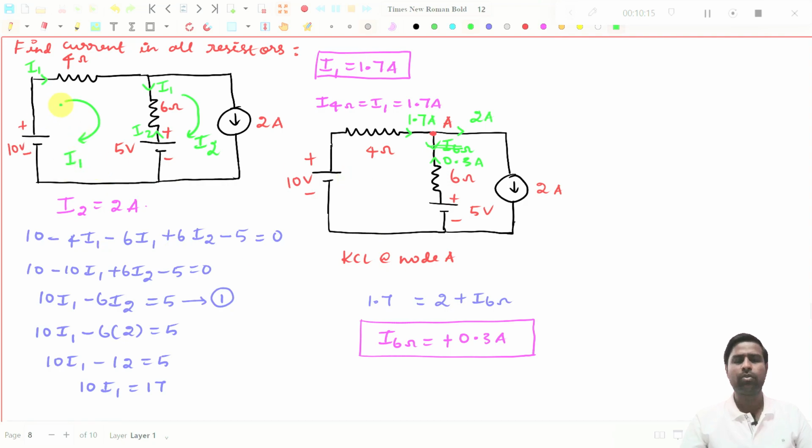And now you see, if you see any current sources in any one loop, particular loops, then you don't panic. The value is already given. That loop current is already given. This will be also applicable if this current source is only in the first loop. Then you have to take that I1 is equal to 2 amperes directly, right? So this is one kind of problem, right?